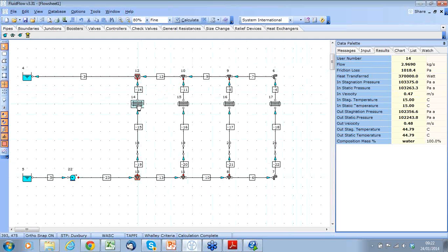Okay. So I can now look at my heat exchangers, and I can see the design condition in my rough hand calculation was a design temperature change across the heat exchanger of 30 degrees, and you can see now that the software is telling us that the inlet fluid temperature was 15 degrees C, which we had set down here, but the temperature or the heat energy change across the system gives us an outlet temperature of 45 degrees C. So you can see that's been applied now to this system.